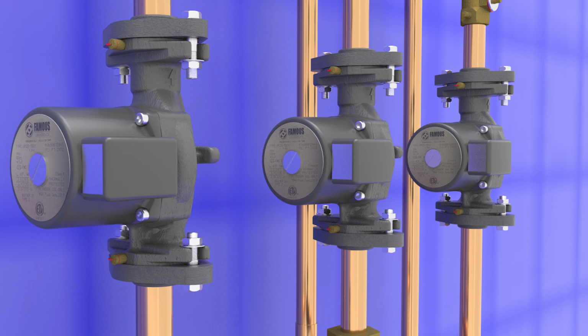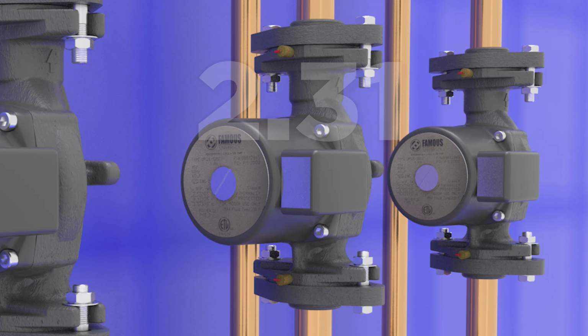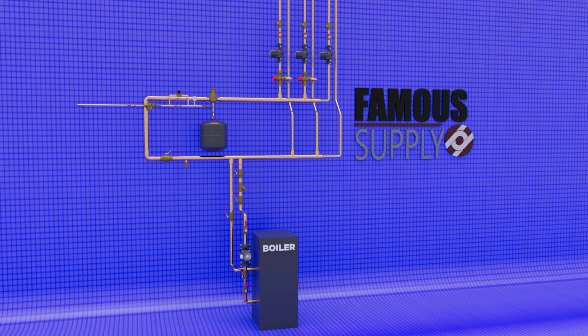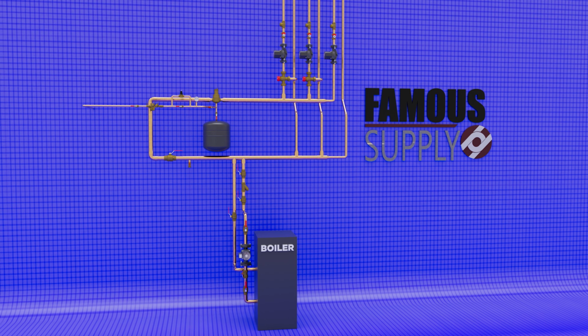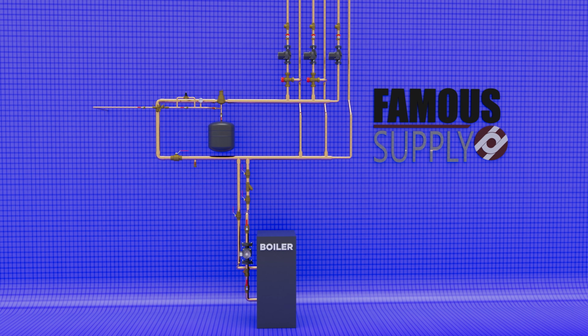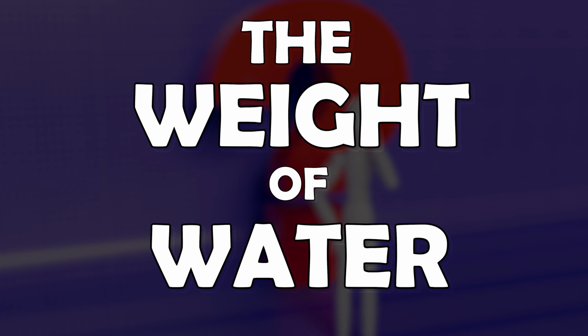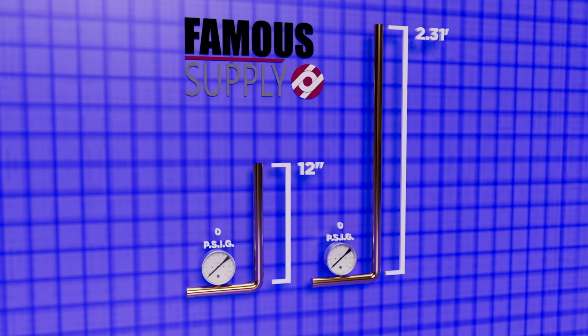When we size circulators, there are two important numbers to remember: 2.31 and 0.4332. These are constants or known values that we use in our math to determine how much force we need to generate the correct amount of flow. But what do these known values represent? The weight of water.